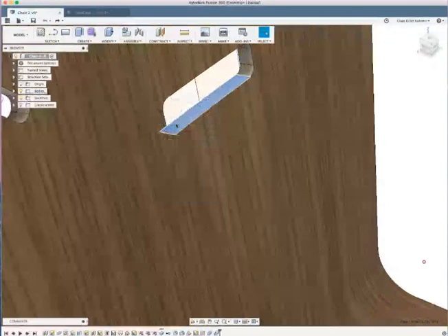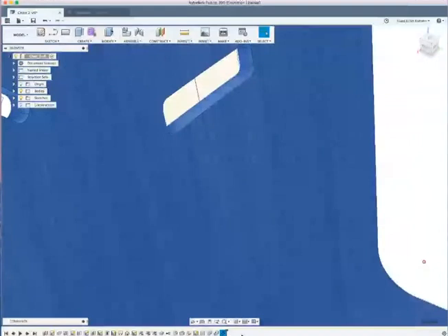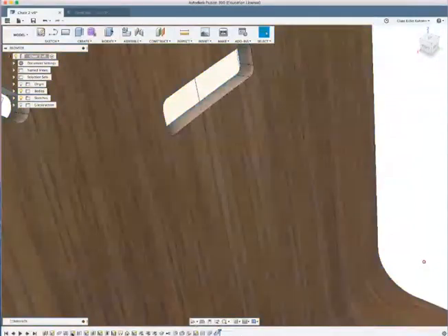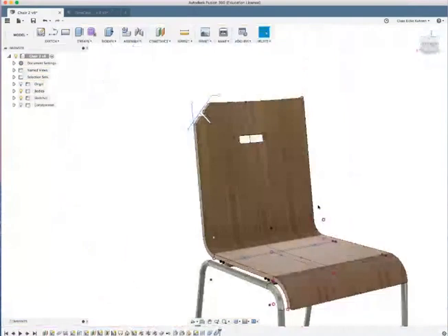And then the software will actually capture also this move command. That is a problem I see very often with people who work with parametric modeling and then later they want to do adjustments because they don't want to adjust everything inside the feature tree. And those manipulations, when done a lot, can actually make it very confusing to read the feature tree.